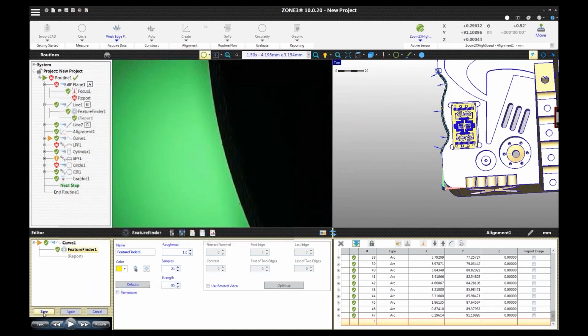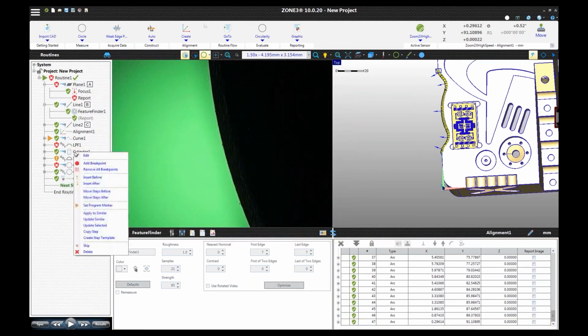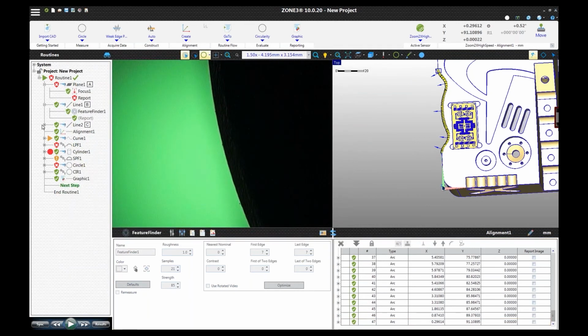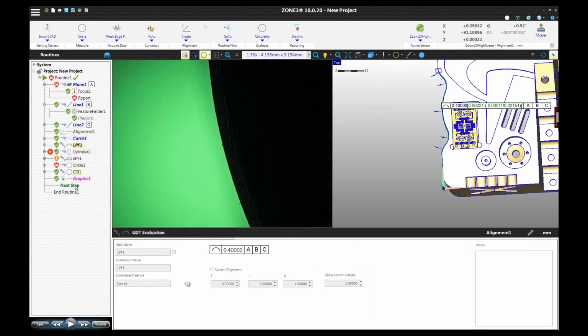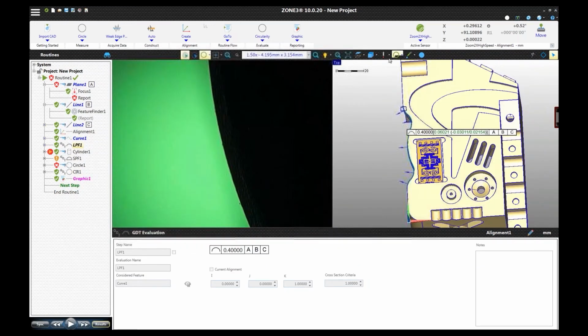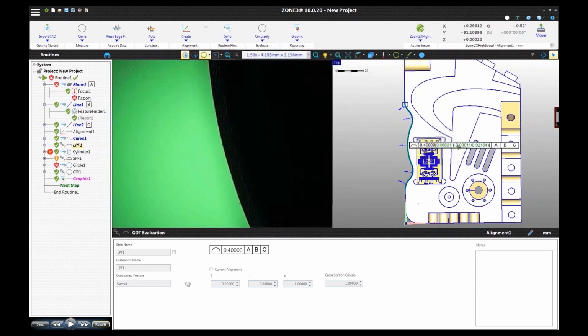So now I'm going to go ahead and save that. And let's rerun this profile step here, just that. And now it looks like it's passing. Happy days, okay? That was the problem, those 2 deviations and those couple of bad points there, and now we get a passing measurement. And it was quite significant too. You can see right there, I was at like 430 microns of deviation, and now I'm at 60 is the worst case scenario, minus 30 times 2.